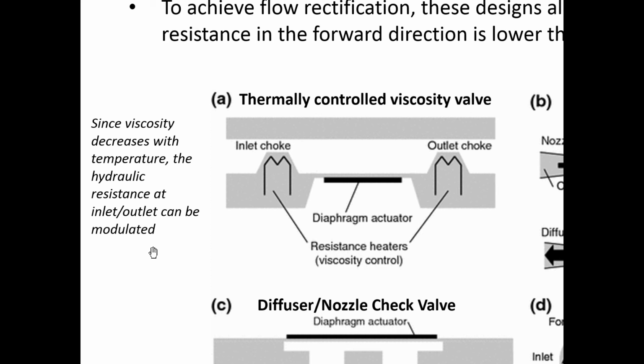So if you were to decrease the viscosity of the liquid, is it easier to move fluid through the channel, or is it harder? It's easier. Right. In fact, there's a linear dependence on the hydraulic resistance and the viscosity, if you look back to the equations we talked about earlier. It's a linear dependence. So flow resistance increases with viscosity.